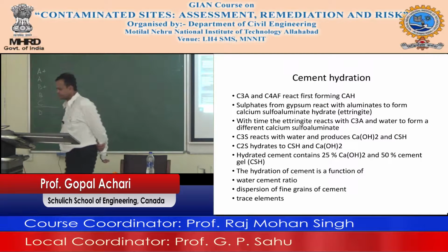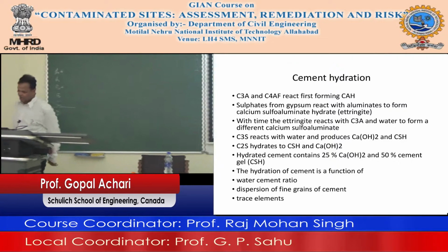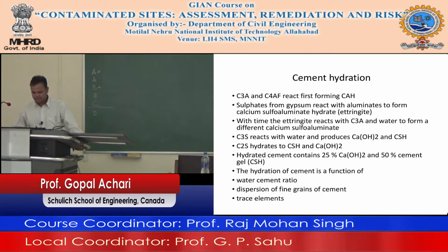Okay. So hydrated cement contains 25% calcium hydroxide, 50% calcium silicate hydrate. Okay. Now, if you take cement, it is very alkaline. If you take the pore water of cement, it is alkaline because of the 25% calcium hydroxide. Okay. Now bear this in mind. Keep that in mind. We'll come back to it in a bit.